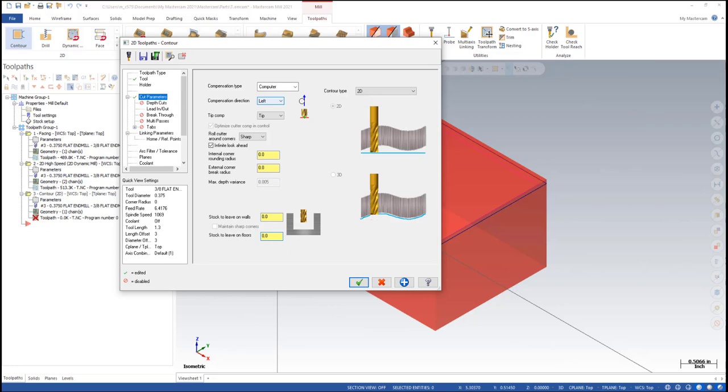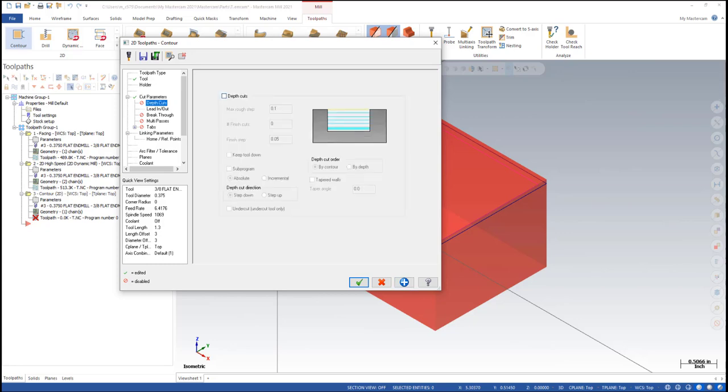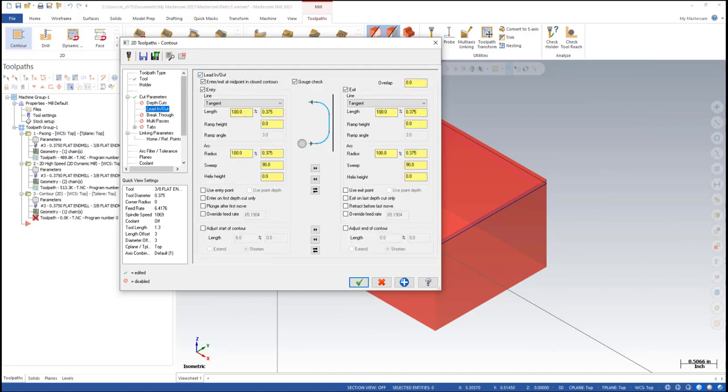But we don't want to have it driving along the floor because it might kind of drag the tip when it's in the cut, and that might lead to a little bit of deflection. On a more rigid machine or a bigger tool, it probably wouldn't matter so much. But we already cut 20 thousandths extra stock on the first operation, so we can go ahead and just add. We'll give it back. We'll use negative stock, but we won't go 20 thousandths. We'll maybe go minus 15 thousandths. So a little bit of negative stock, but not all the way. No depth cuts. We're trying to make this in one pass because this is a finishing operation.